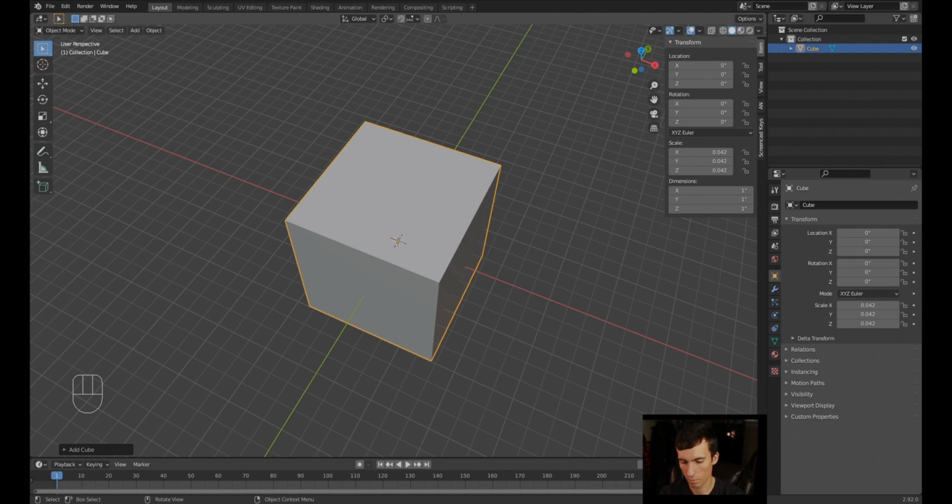And then we got a thickness of, I would go a little bit thicker so it has space. If we're making a holder for an SD card, you want it to be easy to put into the holder and not have to really aim it right. So I'm gonna go with 0.15 of an inch for the thickness. And then we need the width. Width is 0.95. So we have our basic dimensions.